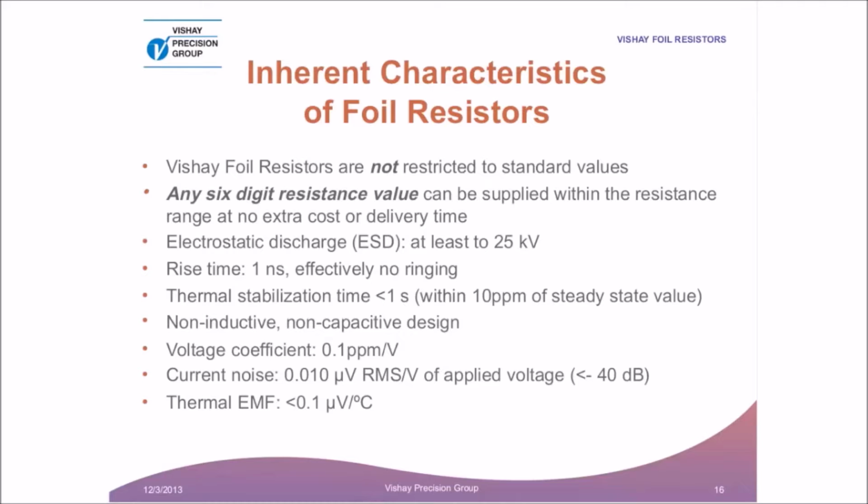We've already mentioned that ESD is good up to 25 kV, very fast rise time, very quick thermal stabilization, a non-inductive, non-capacitive design, very low voltage coefficient, extremely low current noise, and as Richard just mentioned, a very low thermal EMF. The only thing that I would add to this slide is, in actuality, the thermal stabilization is almost instantaneous for foil resistors in almost every application.